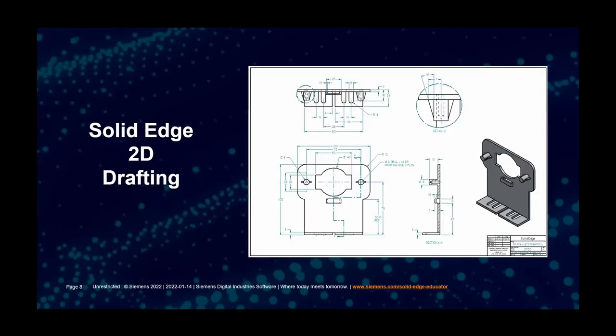And that brings us to Solid Edge 2D drafting. So that is where the 2D drafting comes in. What it allows you to do is offer simple drawing layouts, diagramming, annotations, and dimensioning controls that automatically comply to the drafting standards. That can include, for example, the international standards, which is the ISO, the American standards, ANSI, or the British standards,